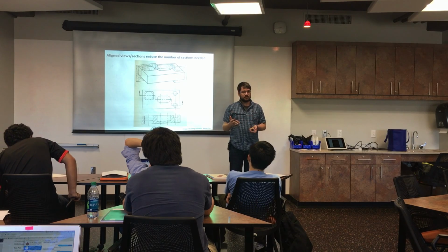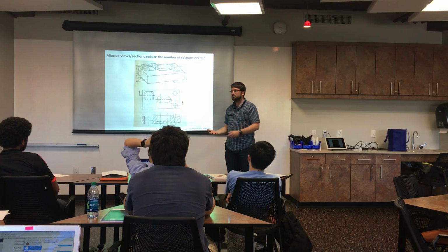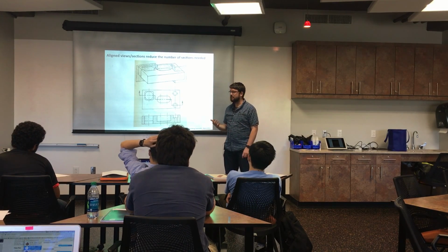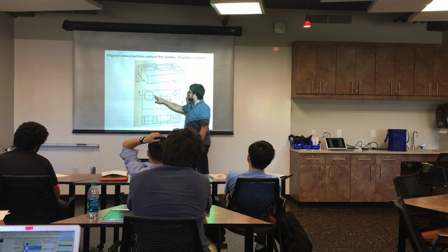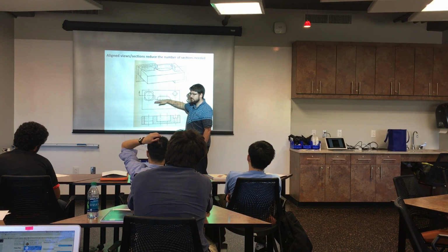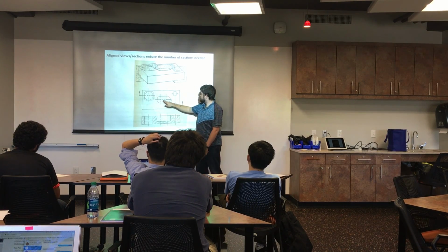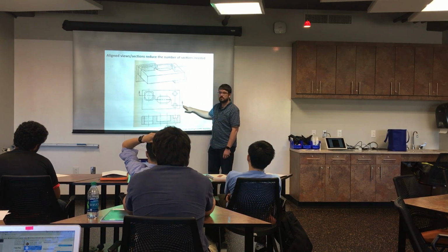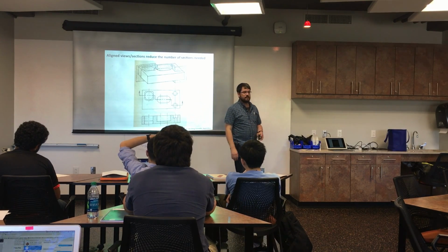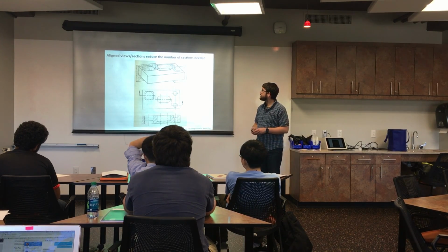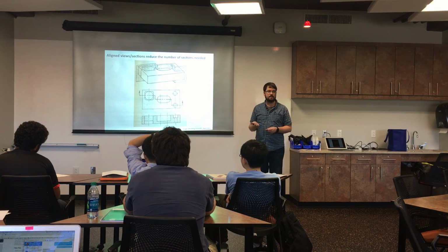It's not a very efficient use of my drawing space, and it has a lot of redundant, unnecessary information. Whereas we can take our section line and break it. So we have these vertical lines where it's like taking this and shifting it up or shifting it down. So we go over here, then we go through this pocket, then we go through this hole. And in section view, it would then look like that. These are pretty common to do on complicated parts, though.